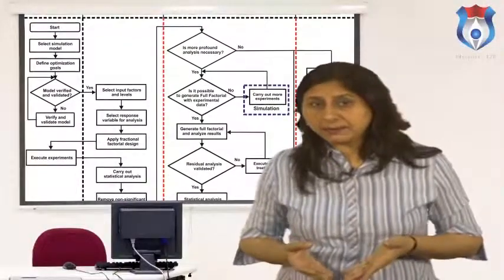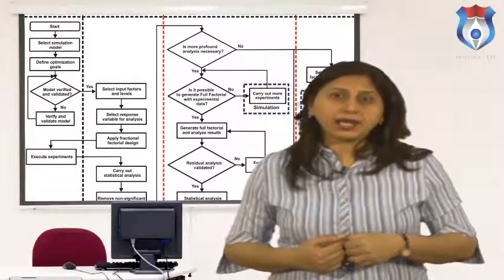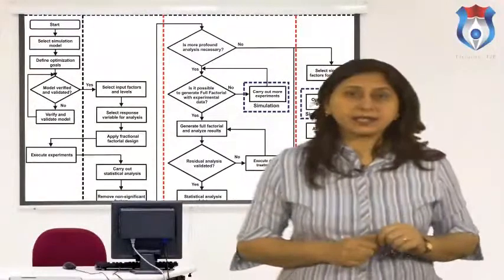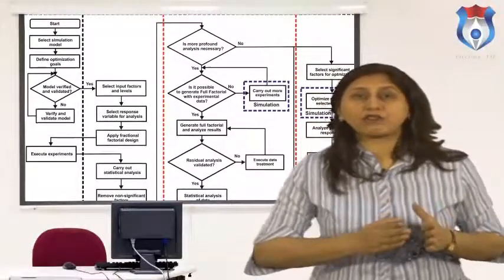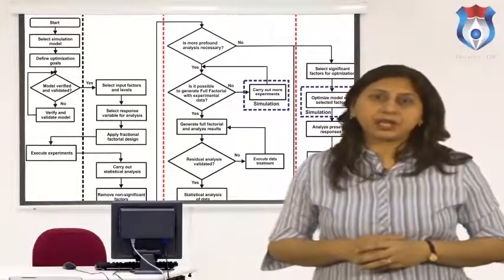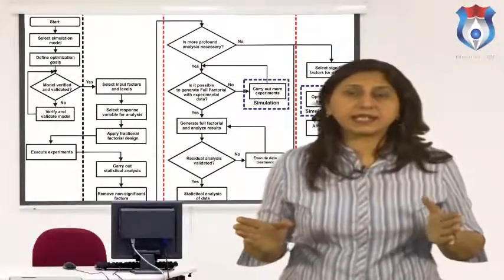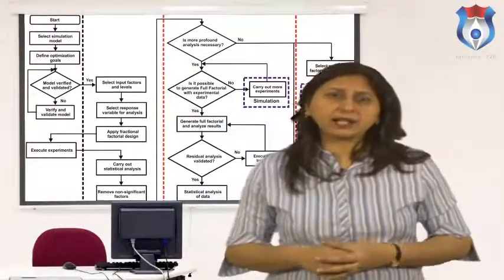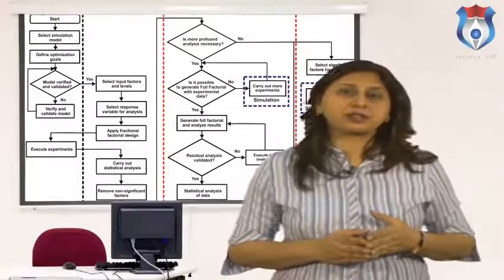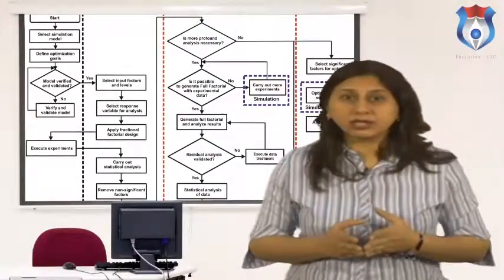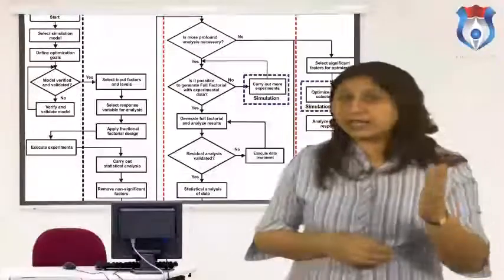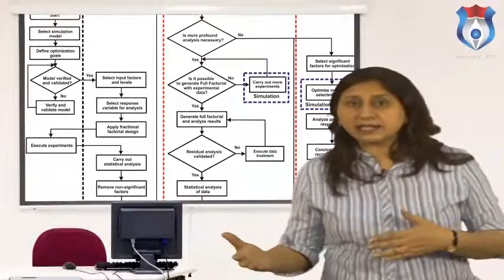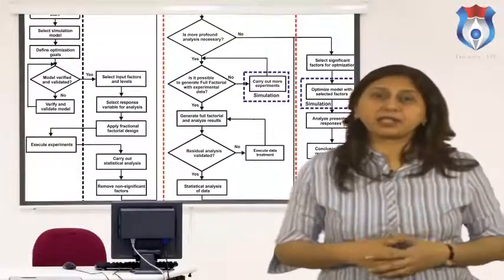Example: processing times, arrival rates, etc. Another key point is to ensure the model is valid, that is, its behavior mirrors that of the original physical system. For systems that do not exist yet, because simulation is used for planning them, this is especially hard. Insufficient validation and verification of a simulation model is one of the top reasons for failing simulation projects. The consequence is false results, and this lessens the credibility of the method in general.